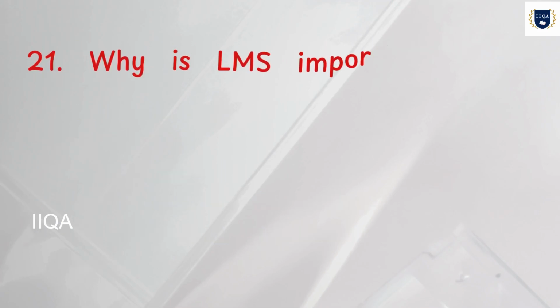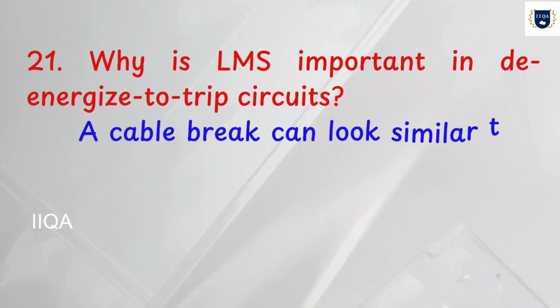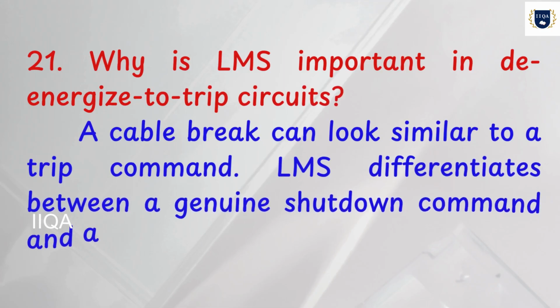Why is LMS important in de-energize-to-trip circuits? A cable break can look similar to a trip command. LMS differentiates between a genuine shutdown command and a wiring fault.